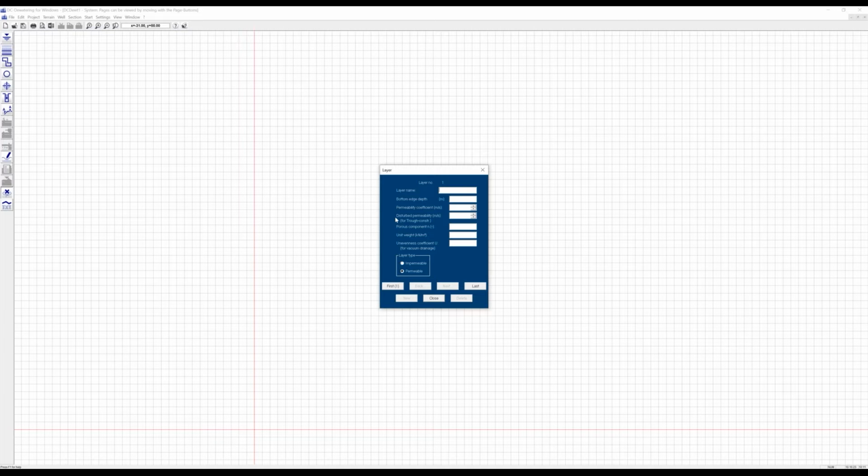So we use only one soil layer, gravel, for example, which is available down to the depth of the aquifer. And for the permeability coefficient, Kf, we can switch with these arrows over factors of 10. For example, if we want to have 5 and 10 to the power of -4, we can switch with these small arrows.